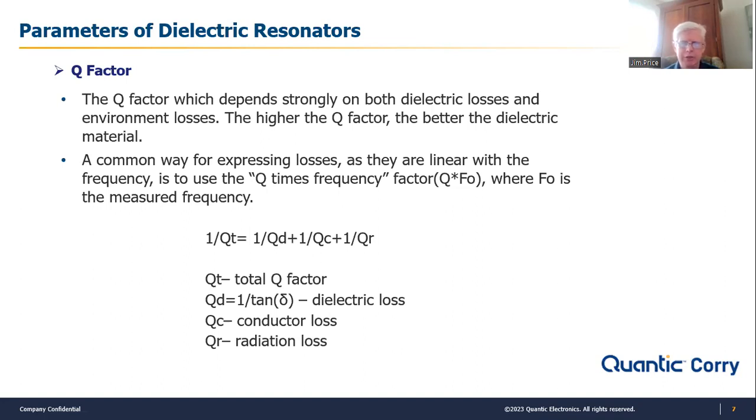And for that reason, because you can't radiate much energy from the dielectric resonator to the outside world, that hurts the total bandwidth you might be able to get from a bandpass filter. Remember how I said that you want to couple a lot of energy from rod to rod if you want a wideband filter? Well, you can't couple a lot of energy from resonator to resonator if most of it's contained inside the resonator, and it tends to not want to radiate outside the resonator.